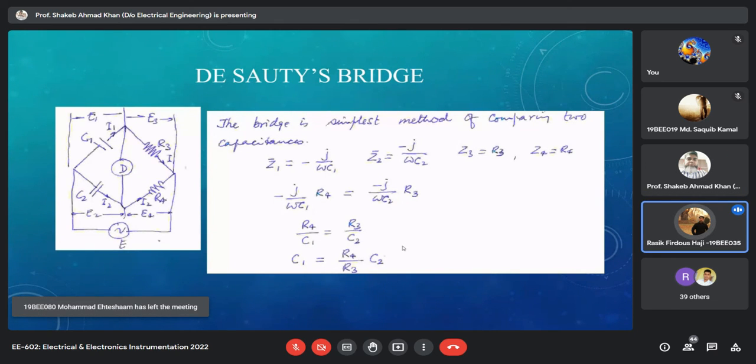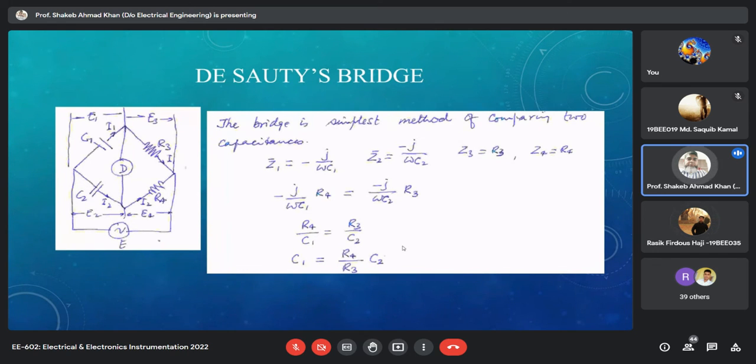Sir, other than ideal capacitor, you talked about lossy and lossless capacitance. A lossless capacitor will be an ideal case. But sir, in practical ways, we will never get a lossless capacitor. So it will never be used. It's not never, you can have air capacitances where the air is used as a dielectric, so you can consider them as lossless capacitors. They are very good capacitances. So it is not like that you cannot have lossless. We generally want that your capacitance should have minimum losses.